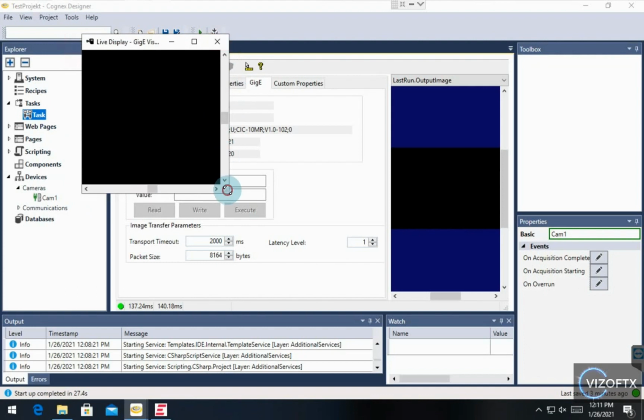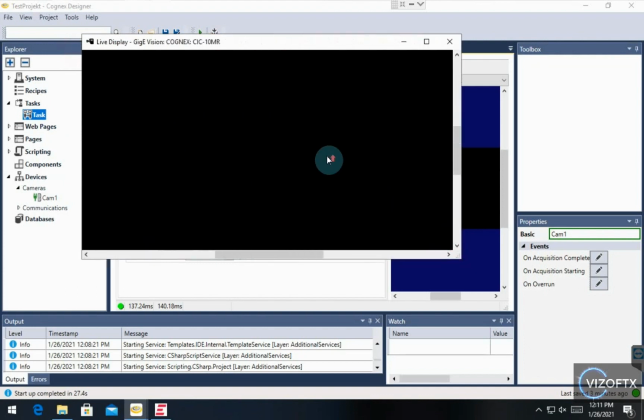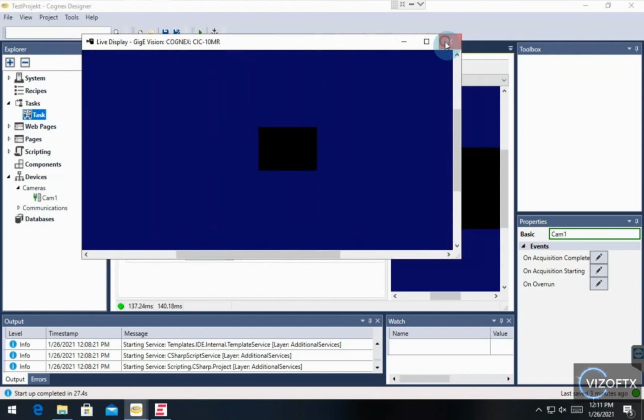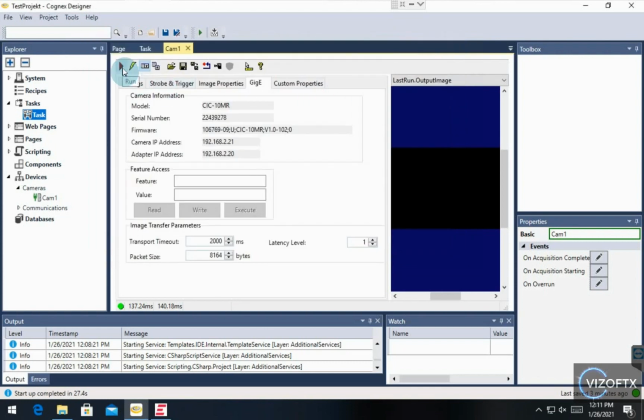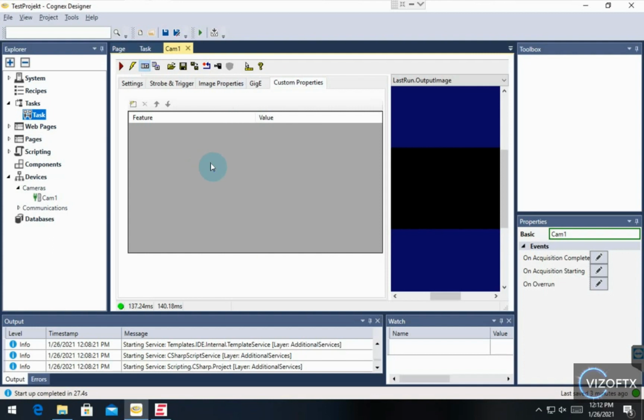I do not recommend using this live display for high-resolution cameras because the VisionPro does not handle this live display so well, and sometimes it happens that the whole program freezes. It worked like this for us at 20 megapixels, so I think even higher it will work like this if it was not fixed in newer versions. Other solutions to problems with GigE cameras imaging and internal camera settings that can be done here will be shown in special parts later on.